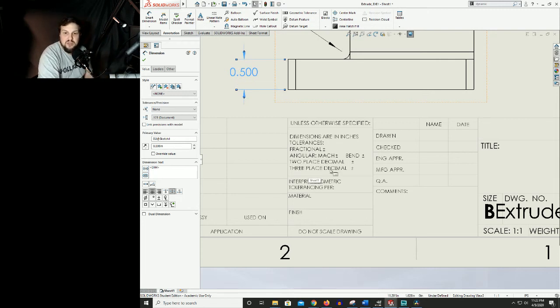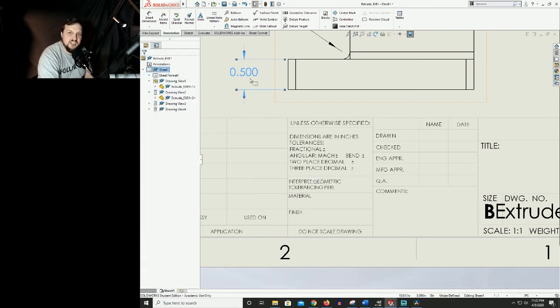For 3 decimal places, we could modify this. Because it's got 3 decimal places in it, this is only 15 thou up and down, which is halving the size of our tolerance gap. So now we've got 0.485 to 0.515, and it's tightening that in. It's saying that we need this to be a more precise number.